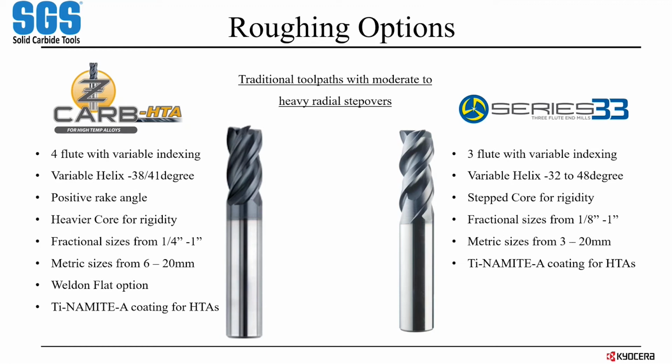My opinion, this is one of the more underutilized, if not the most underutilized tool in our portfolio. It's a great tool, especially if you're doing tight pocketing, something where it really needs to dig into a corner. That 3 flute design really helps cut down that stress and load from less contact with the workpiece there. So you get into a high flute count tool and you try to dive it off into a tight corner, you're going to get chatter. That tool is going to want to bind up a little bit because that engagement is spiking as it gets in there. And this tool really combats that very well.